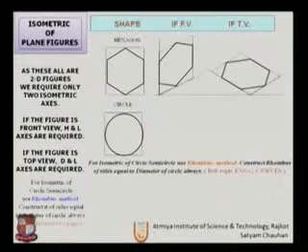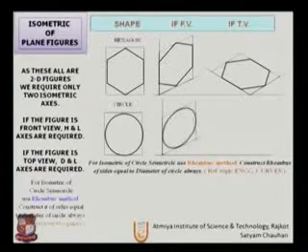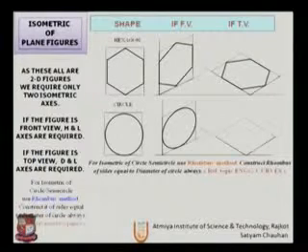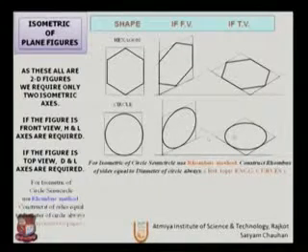So construct the rhombus of a side equal to the diameter of the circle, and the reference will be here. As we learned, draw the axis first and then the square and then complete the rhombus to complete the arcs as we have seen before.